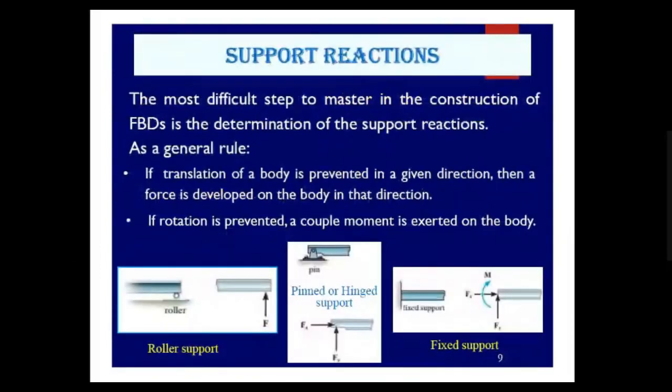Now, in order to understand the reaction forces, we must first of all understand what the different types of supports are that we may encounter in the real world. The most difficult step to master in the construction of a free body diagram is the determination of the support reactions. As a general rule, if translation of a body is prevented in a given direction, then a force is developed on the body in that particular direction.